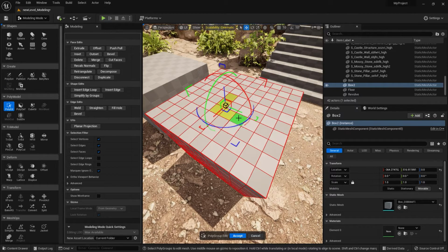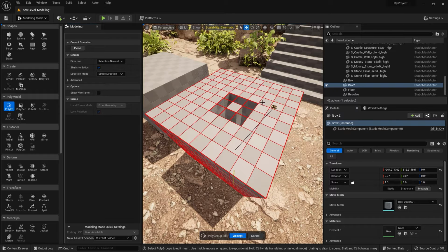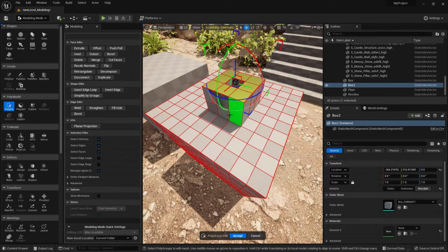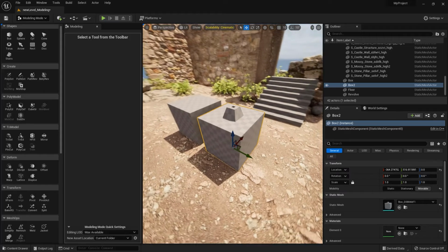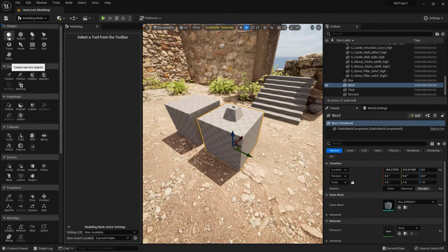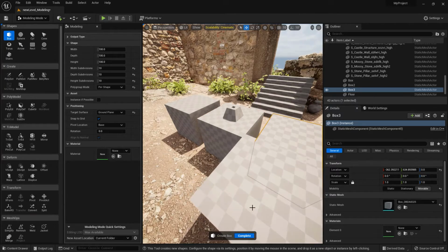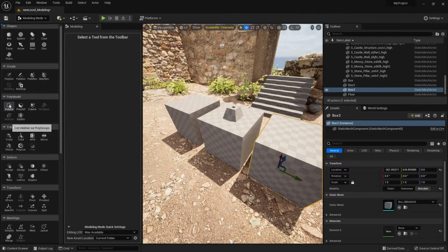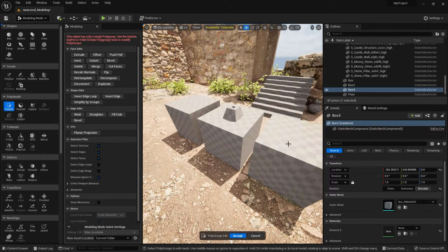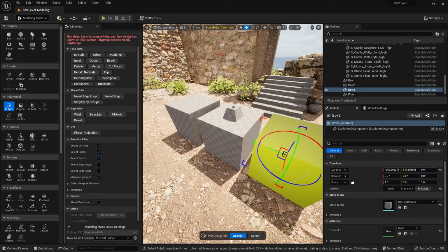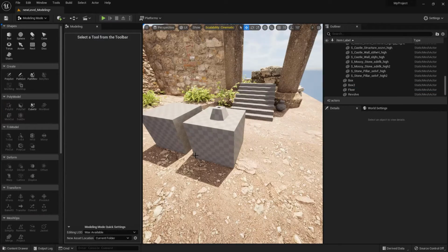I can actually select a bunch of polygroups, go in there and apply a tool like extrusion, and with that selected I can just go ahead and modify it. So again, the importance of polygroup is extremely important. There is a third mode in polygroups, a ready-to-go preset polygroup, and that is per shape, which turns the entire geometry into a polygroup. Now if I go in here and go to Poly Edit, hover my mouse, all of a sudden everything is one polygroup.